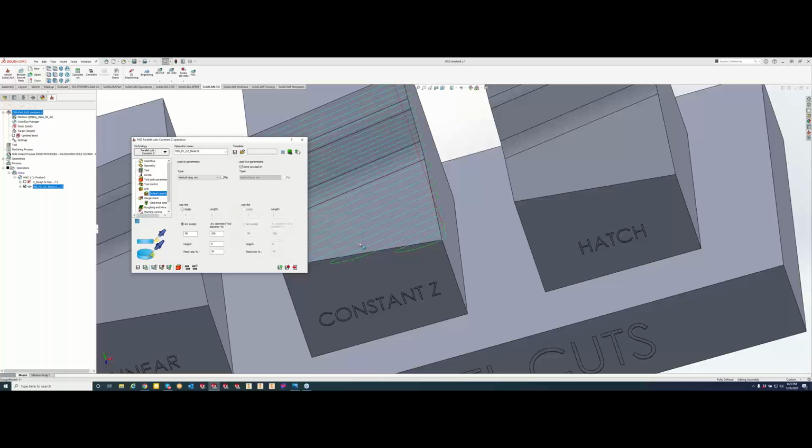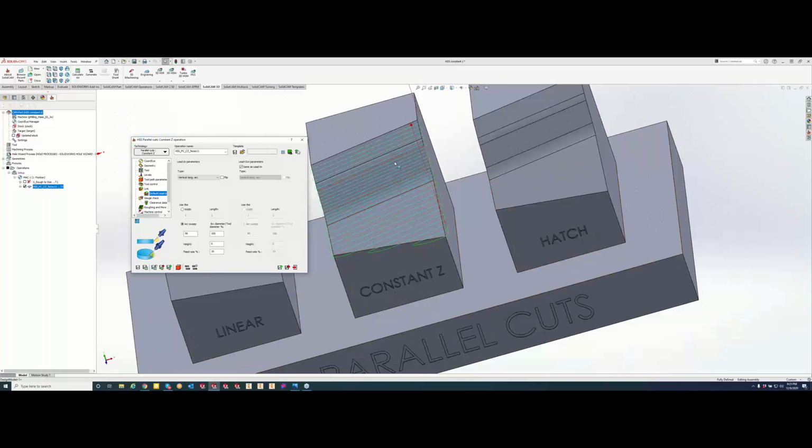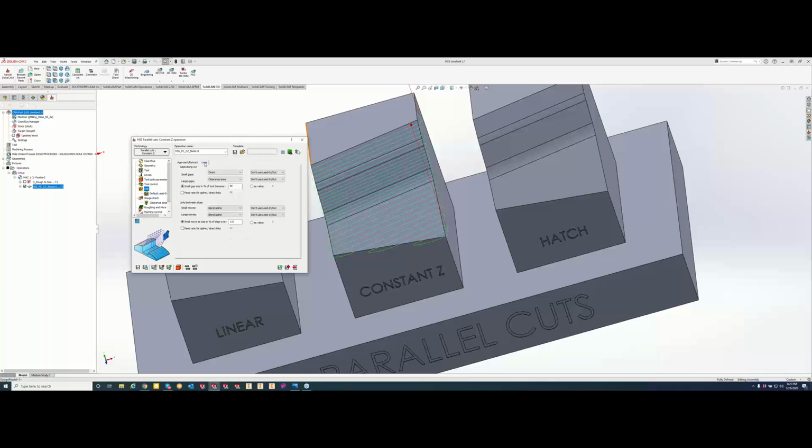With those selections. And one thing, Greg and I stress this all the time, is once you get something comfortable in here that you like, you like seeing the tool path, everything set up, save it out as a template so you guys don't have to go through and reset up any of this stuff again. For myself, the first thing a lot of times is I'm coming to the link section and switching these over to a blend spline, because 90% of my tool path, that's what I'm having to do. So like I said, save that as a template and put that as your default if it's something that you use all the time. So when you go to load up this HSS operation, it's already set up for you guys.